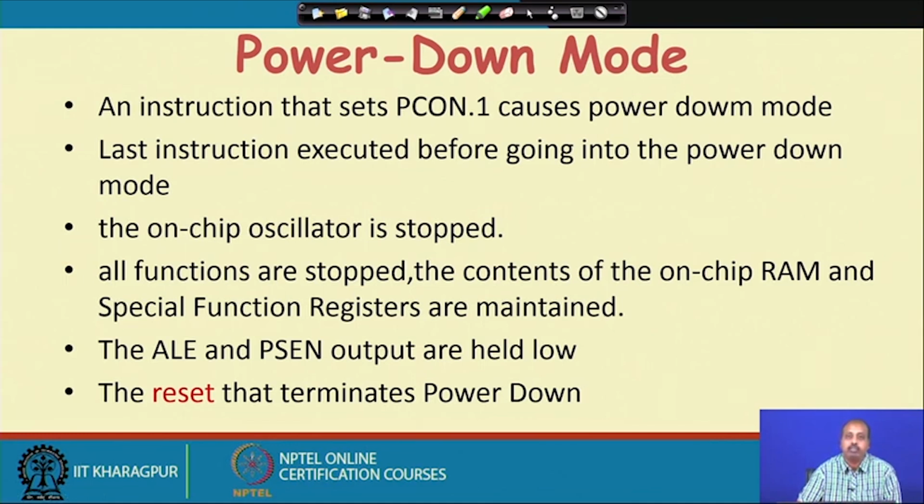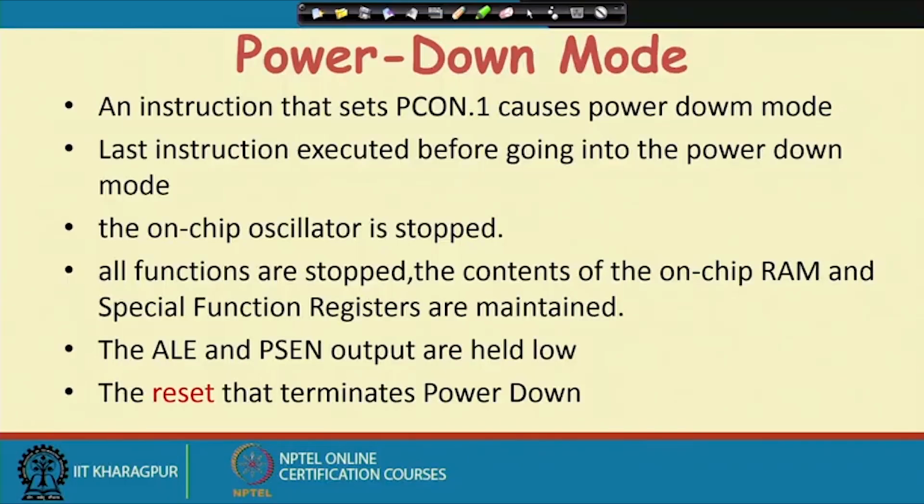designing systems where we need to save the battery. In most cases microcontrollers are used for embedded applications where battery life is important. So we can use these processors for doing these things. We can put the device in power down mode or in idle mode when the operation is not required, and whenever the service is required, we can turn on the device or turn on the services.